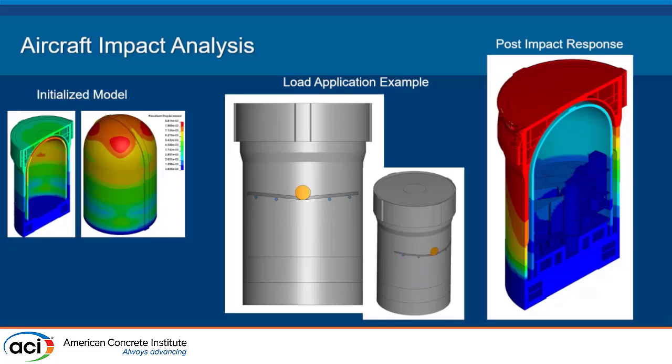This is for a reactor building where it's a double-walled structure, a very heavy outer structure that is designed to take most of the aircraft impact. And then the inner containment, which is cylindrical with a spherical dome on top. Hopefully, that's never engaged, but this is all very heavy-duty reinforced concrete. There's even a steel liner on the inside of the containment building to catch any scabbing products. The inner container even has pre-stressing tendons to put it largely into compression when initialized. And so we go through all of those steps before we add our insult on it.